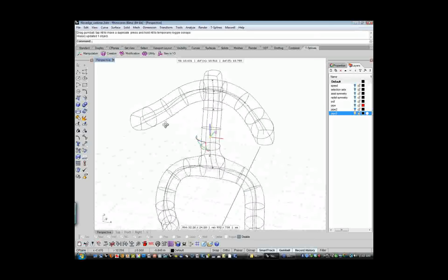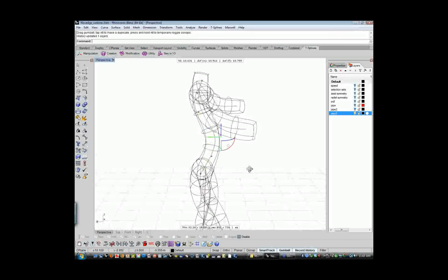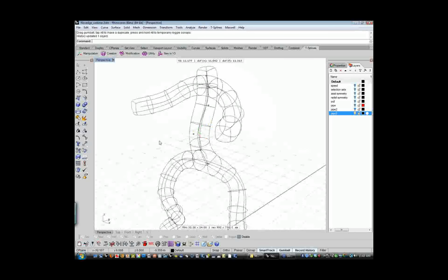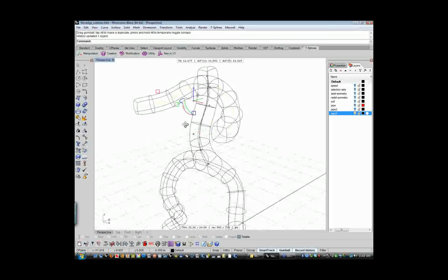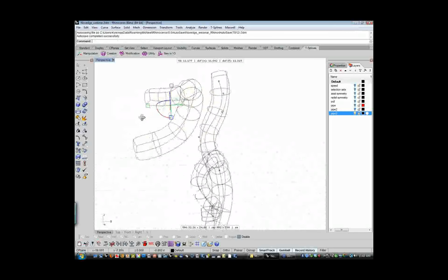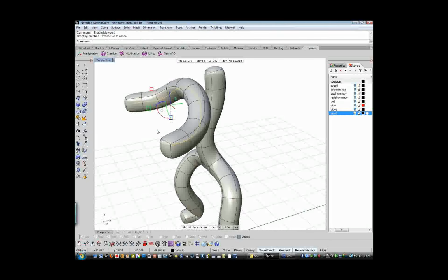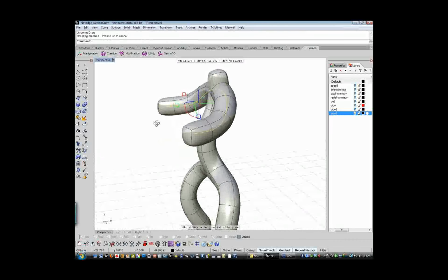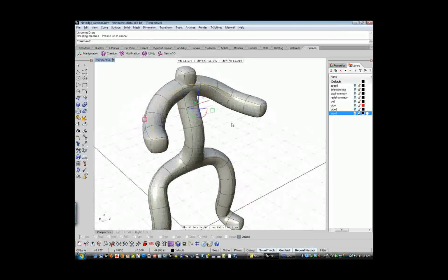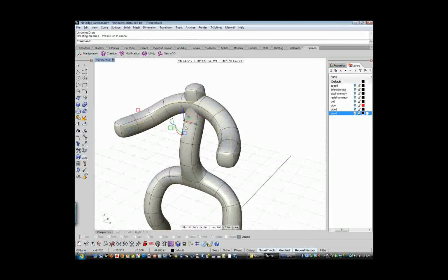Oh, I like that. You're keeping that secret, weren't you? That's awesome. Kyle, you can even grab one of those curves that doesn't have the control points on, and move that curve out so it's not intersecting anymore. Wow. You want to go shaded mode, but it will undo that. It'll break apart the T-spline, and if you move it back, it will intersect again. You have to make sure that it actually touches exactly. I don't think those are touching.